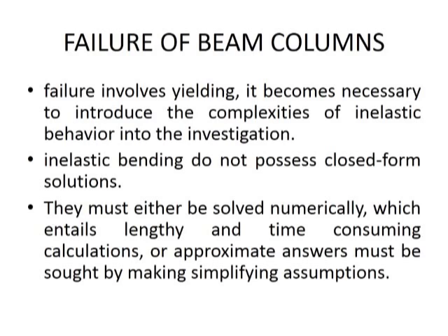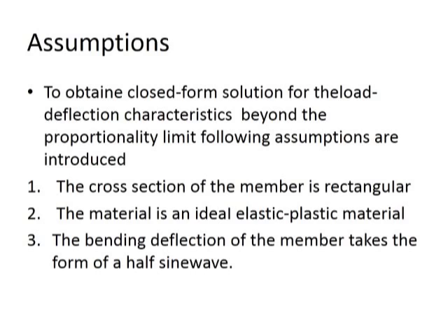Coming to the failures of beam column, failure usually occurs by yielding. It becomes necessary to introduce the complexity of inelastic behaviors into the investigation. Inelastic bending does not possess a closed form solution. It must either be solved numerically, which entails lengthy and time-consuming calculations, or approximate answers must be sought out by making simple assumptions. And these assumptions include: